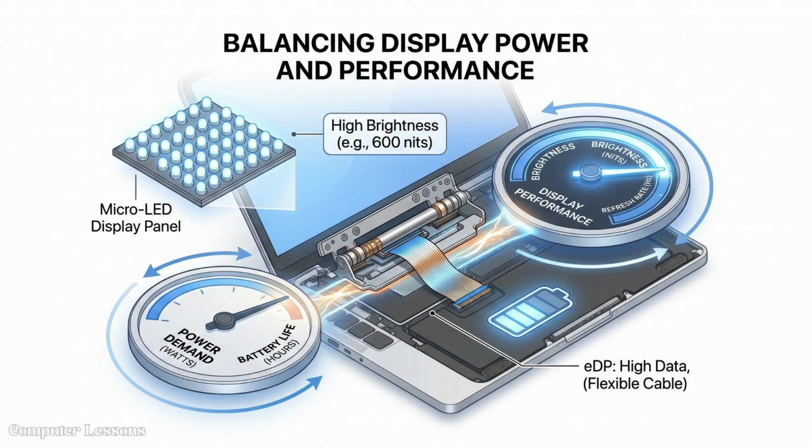Display engineering in laptops utilizes embedded DisplayPort interfaces to drive high-resolution panels through thin, flexible cables in the hinge. Manufacturers must balance panel brightness and refresh rate against total power draw. Every extra nit of brightness reduces the total battery life of the system during mobile usage.